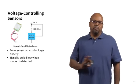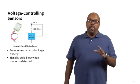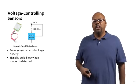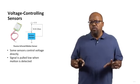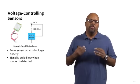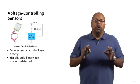Now, when it doesn't sense motion, it doesn't do anything to that wire on top, right? So the voltage on that wire would be floating. So that's why we have that 10 kilo ohm resistor to power. Because one thing that we never want on an input to our circuit is a floating voltage, a voltage that we can't tell if it's high or low, right? We don't want a floating voltage.